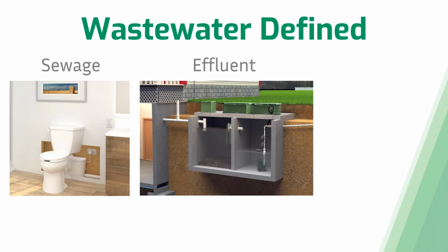And usually inside of the septic tank, you're going to have your wastewater come in, and then all of your solids are going to sink to the bottom of the tank, whereas all of your fats, oils, and greases will float to the top of the tank. And in between the two is going to be your effluent, which is what is going to be primarily pumped out of that system. So you're really leaving behind all of those problematic solids and fats and greases and only moving the wastewater from that system.